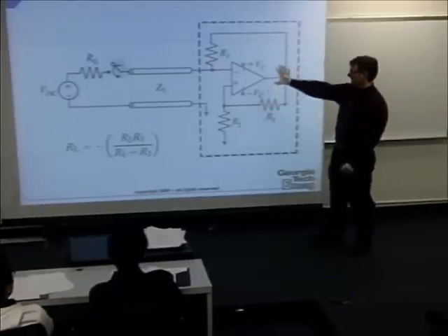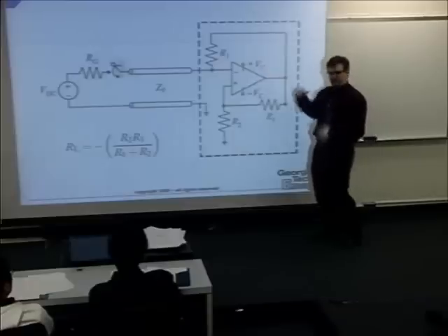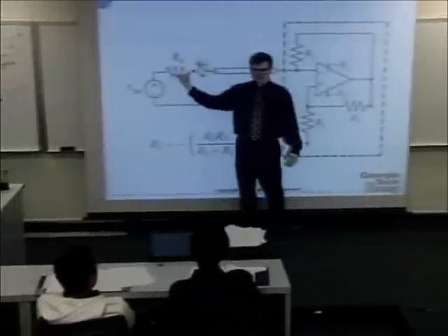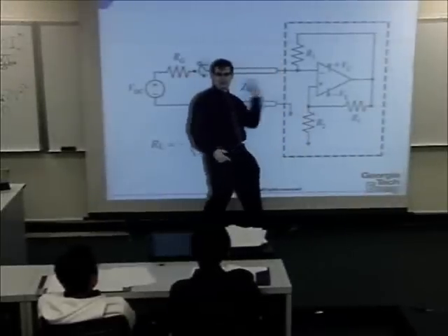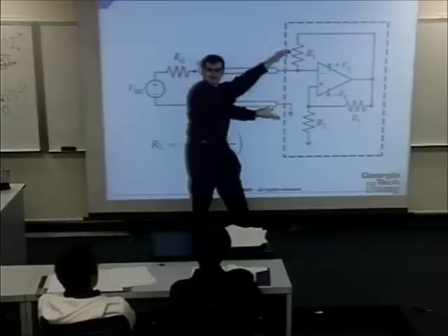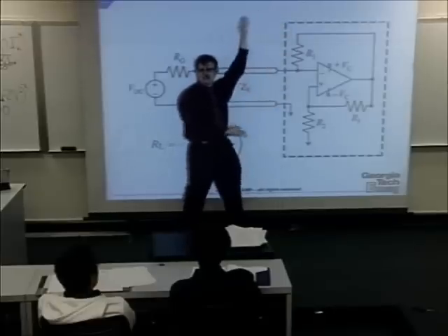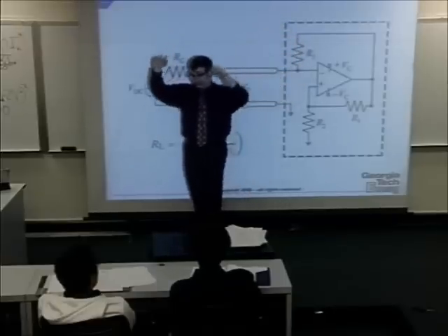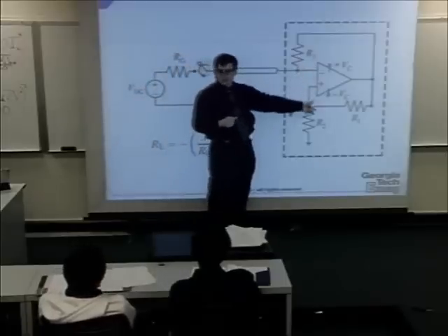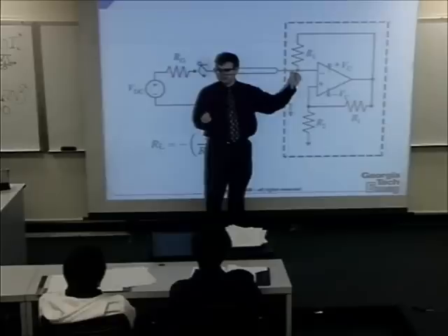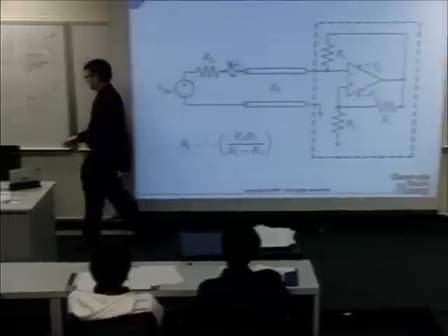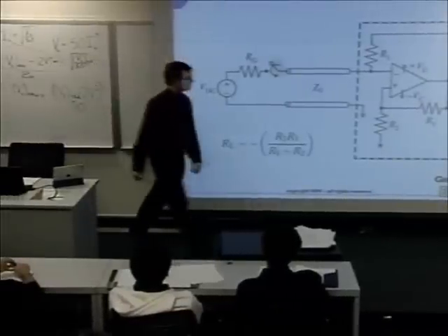Now, intrinsically, you can't do that forever with this circuit. You could conceivably think of a circuit where you had a really bad mismatch up here, and you could build up an unstable reflection: it goes down, gets bigger, comes back, reflects back, gets bigger, comes back, and then the circuit blows itself up. But of course, we know that's not going to happen because this thing has a set of rails on it that are finite, right? If you looked at the VI curve of this device,